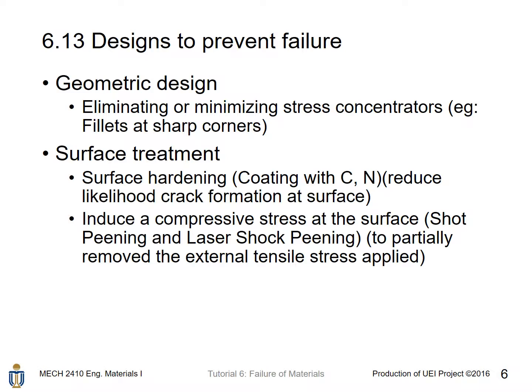Another method is to introduce a compressive stress at the surface, for example using shot peening and laser shot peening, because compressive stress is already induced at the surface. When the applied load is an external tensile stress, it can partially cancel the external tensile stress.